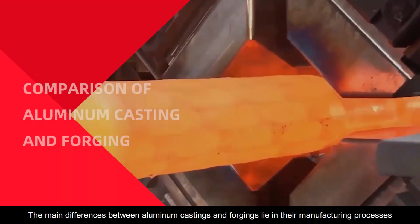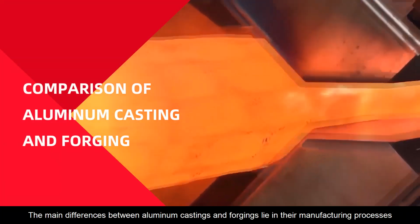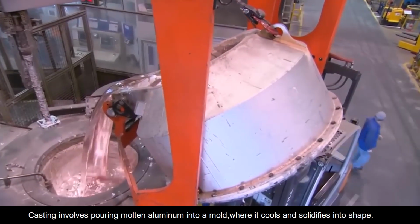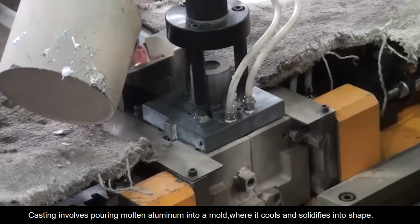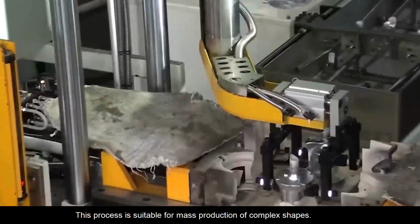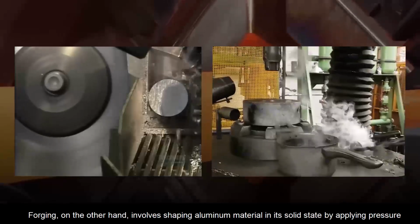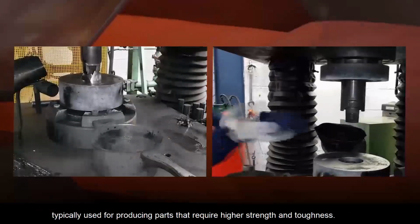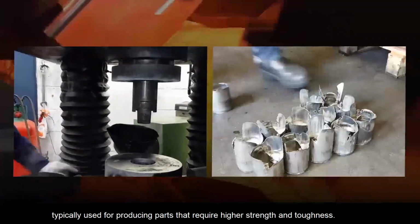The main differences between aluminum castings and forgings lie in their manufacturing processes and the performance characteristics of the final products. Casting involves pouring molten aluminum into a mold, where it cools and solidifies into shape. This process is suitable for mass production of complex shapes. Forging, on the other hand, involves shaping aluminum material in its solid state by applying pressure through hammering, typically used for producing parts that require higher strength and toughness.